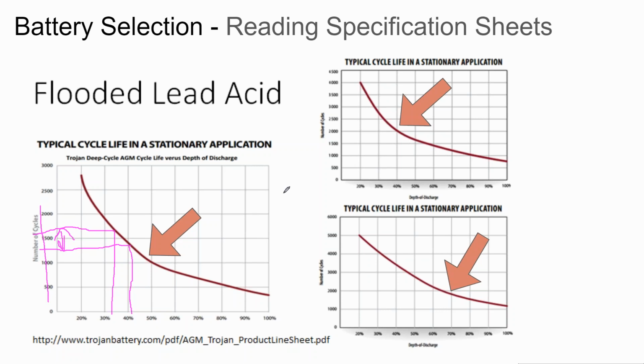So when we talk about oversizing with batteries, erring on the side of caution is not really going to waste your money, in the sense that if you oversize the battery bank, you get a longer life out of it. If I put too much inverter capacity and I only have a small solar array or a small load, I've spent more money on my inverter than I have to. I don't get a real benefit out of it. But if I overspend on my battery in terms of capacity, it just means it's going to last longer.